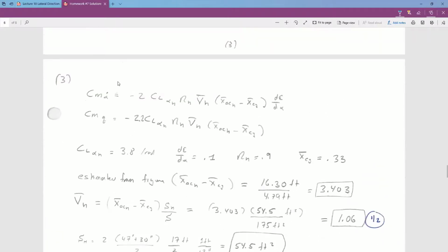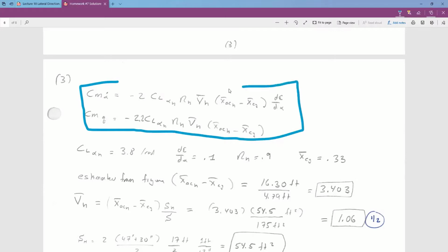So here are the 2 equations from the vertical tail, I keep saying that, horizontal tail effects. We need the moment arm, horizontal moment arm, and this is non-dimensionalized with respect to Q bar S. We're going to use 8H of 1, here's CL alpha H, and then we need the distance from the CG to the aerodynamic center. So this is where your answers may be slightly different than mine.